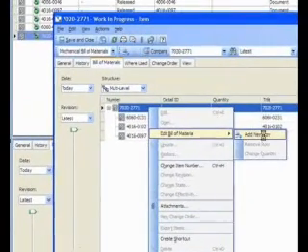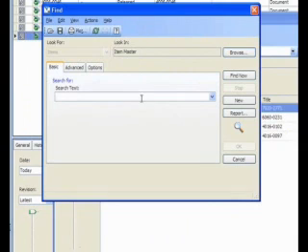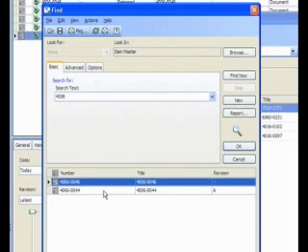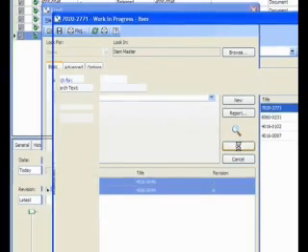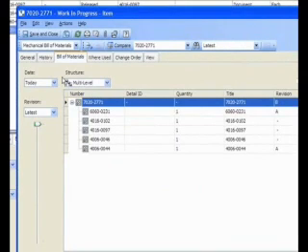We want to edit the bill of material to add new rows to its structure. We will search for the item to add, looking for new items starting with 4006. This list of items is returned. We highlight 2 of them and click OK to update the BOM structure. As you can see, the 2 items were added.